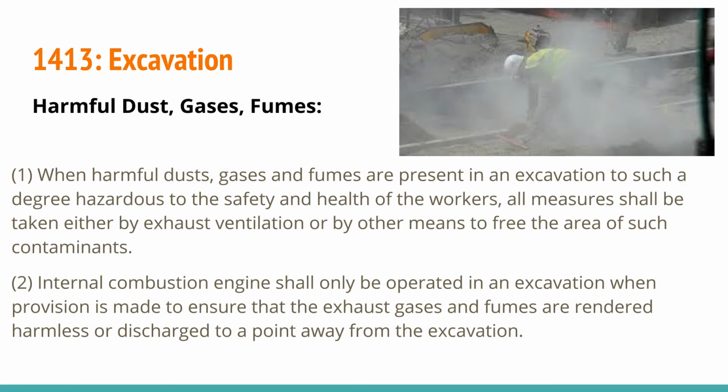So, there are always harmful dust, gases, and fumes during excavation. So when harmful dust, gases, and fumes are present in an excavation to such a degree hazardous to the safety and health of the workers, all measures shall be taken, either by exhaust ventilation or by other means, to free the area of such contaminants. Internal combustion engines shall only be operated in excavation when provision is made to ensure that the exhaust gases and fumes are rendered harmless or discharged to a point away from the excavation.